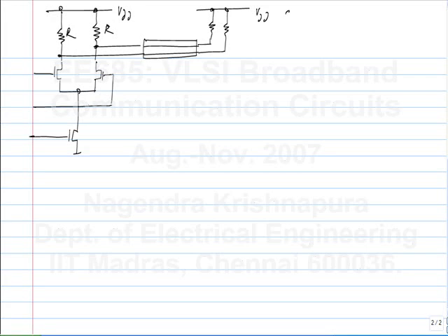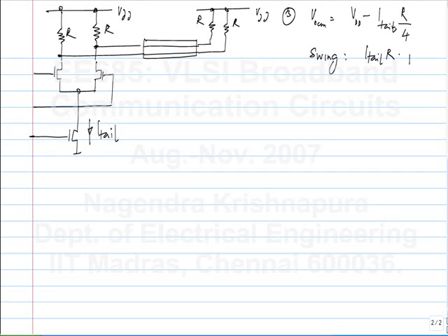So in this case, it is VDD minus I tail R by 4. Both the common mode and the differential currents are terminated to VDD through resistances. So this will give you a higher common mode voltage. That's actually the only virtue of this, that it takes the common mode higher. For a given swing, all of them again have the same swing, I tail times R, peak to peak, but this has a larger common mode voltage.